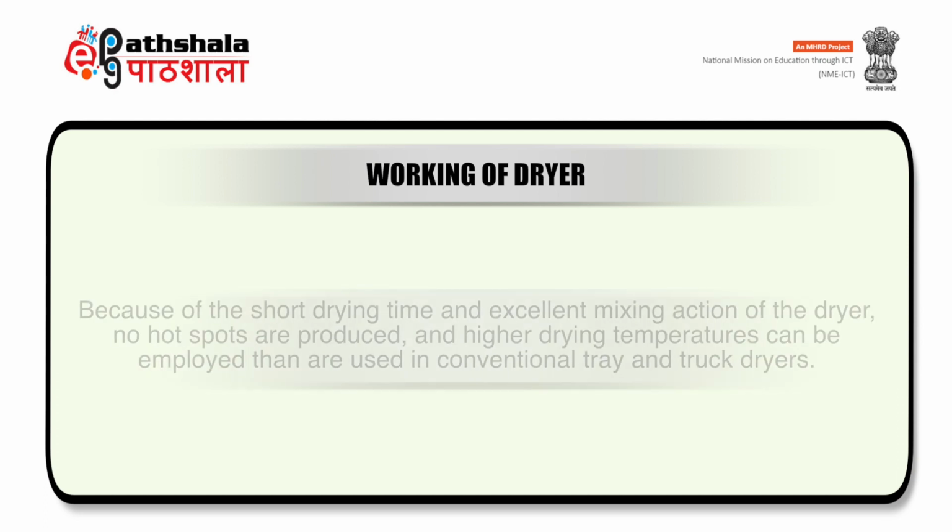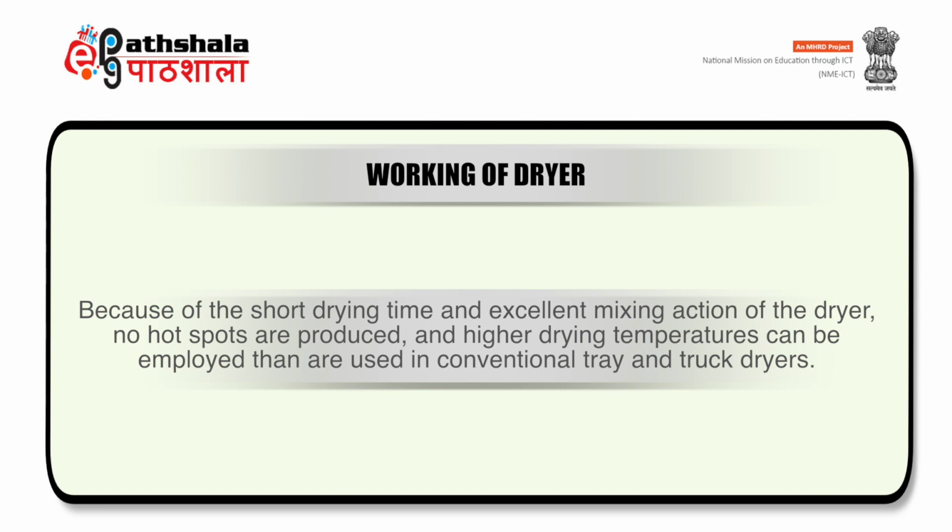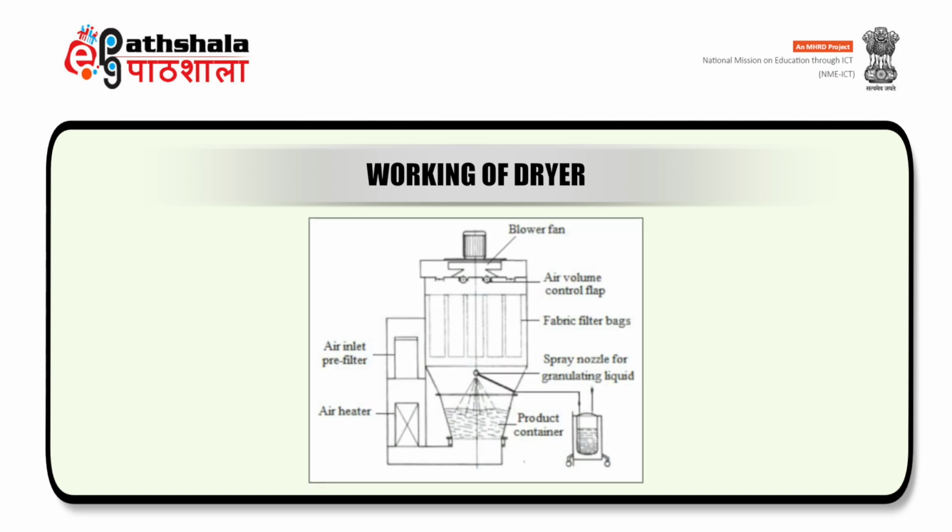and dumping. Because of short drying time and excellent mixing action of the dryer, no hot spots are produced and higher drying temperatures can be employed than are used in conventional tray and truck dryers. The unit as shown on the screen is designed for the direct preparation of tablet granulations as well as for the drying of conventionally produced wet granulations.